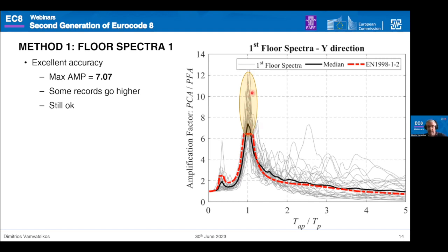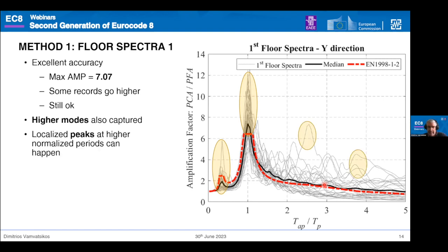But still, again, remember, this is a very, very special situation, a very rare situation. And even if you develop any bit of little ductility in there, which you may as well do, or slippage, this will reduce. So I would not consider this to be a problem, okay? Higher modes are also captured and it nicely envelopes. Okay, it misses a little bit here, but who cares? This happens. And the whole idea is we do not need to be super conservative, it makes sense. So I'd say this is a success.